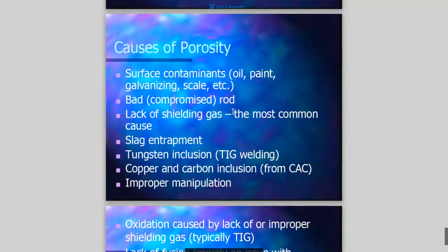So I have a rod oven in the classroom here that keeps rods at about 35, 40 degrees Celsius. But what that does is keeps the moisture out of them. It just slowly cooks off any moisture that might even try and enter the rods. It just slowly gets baked out. So when we take them out of the rod oven, they're great to use. What we can do is leave some out in the middle of the class for a week and then compare them directly with ones from the rod oven, and we can see the difference in the welds. It's not a huge difference, but if you're doing something like a very important structural weld that needs to be completely sound, then it is something you want to do.